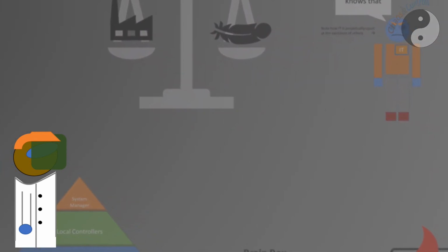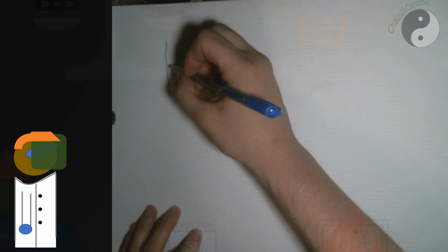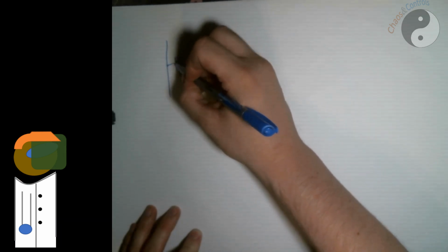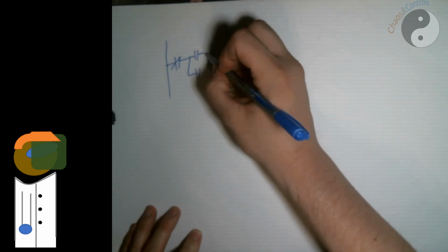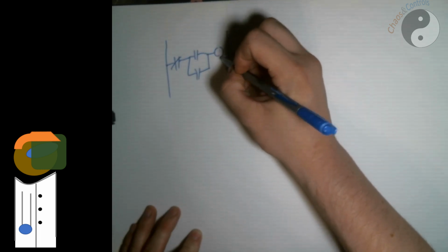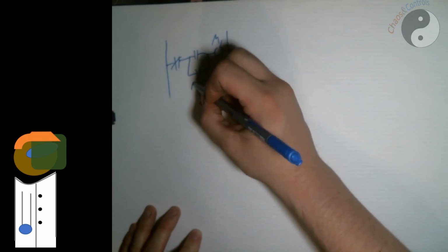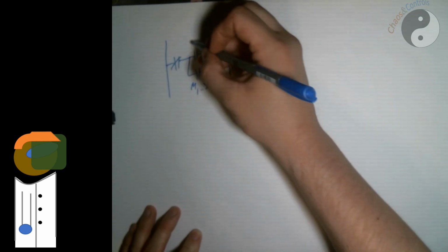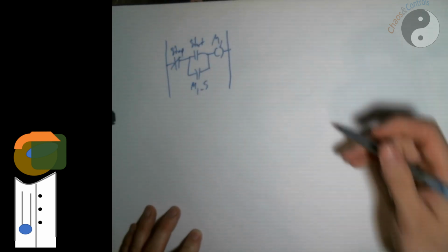I've already discussed a little bit about what we're going to talk about today, so I guess I'm stepping over myself, but you will recall from last time that the classic and quintessential start-stop circuit looks something like this, where I have M1 on a relay, the status coming back from M1, my start signal, and my stop signal.